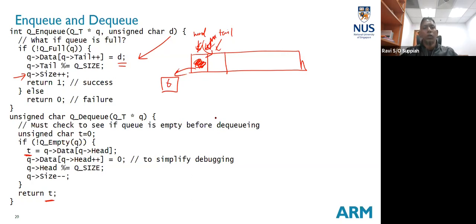Do we need this for the project? It is not necessary. Why? Because in our case, you are going to send one command at a time. If you want the robot to move forward, you send a move forward command. If you want it to play music, you send a play music command. So you will send commands one at a time, and then you decode the command and interpret it. So it's not necessary to use this circular buffer approach for the project.